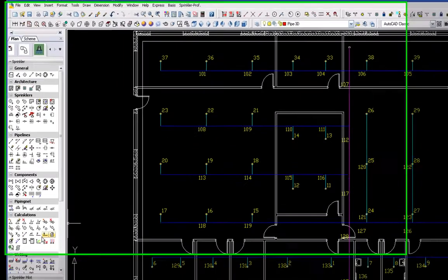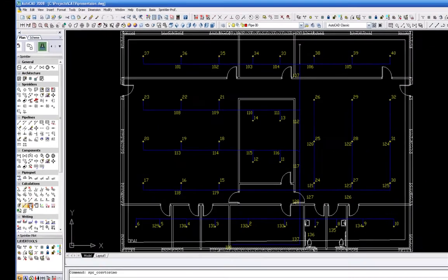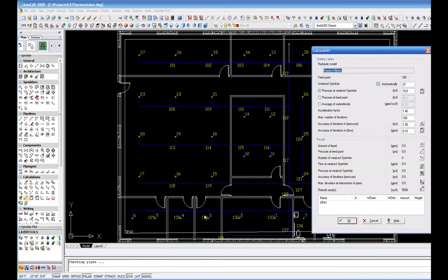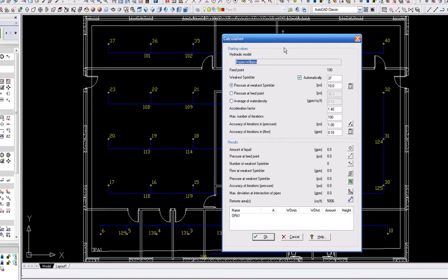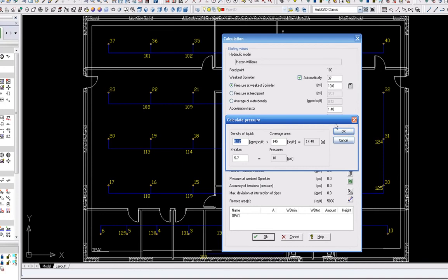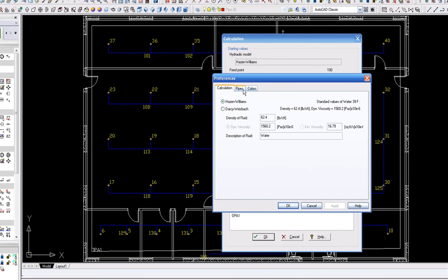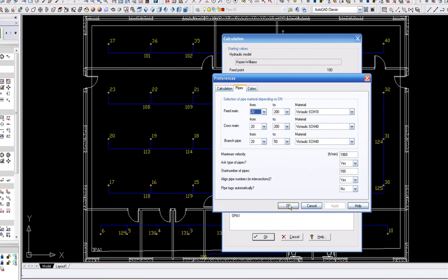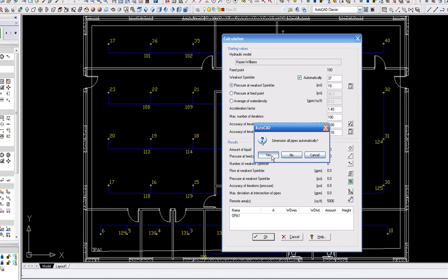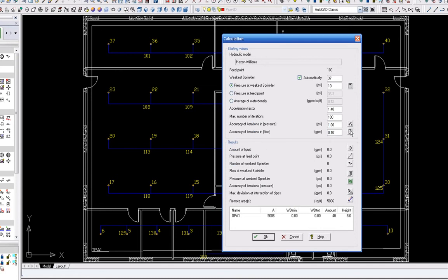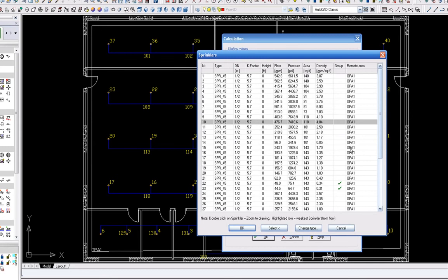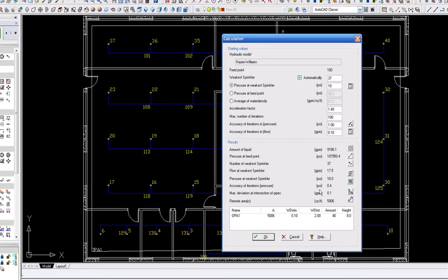Prior to the hydraulic calculation, you have to recheck the starting values. You can modify or select the starting values indicated. Select OK. You will now see the piping lengths, fittings, type, and quantities of the fire sprinkler heads. Calculation data may be inserted onto the drawing at the location where you would like to place it. You can also export the calculation results to an Excel spreadsheet.